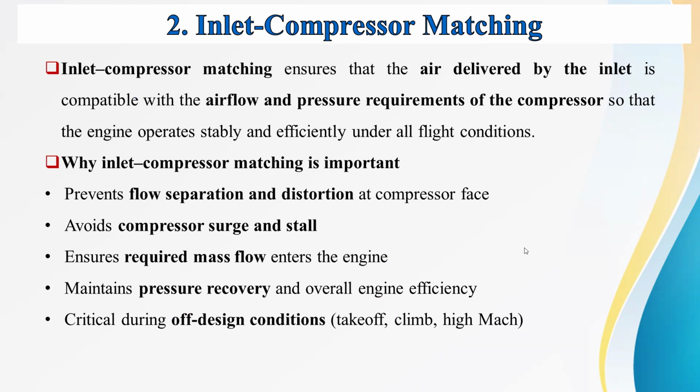Okay, so why is inlet compressor matching important? This is because it prevents flow separation and distortion at the compressor face, and it avoids compressor surge and stall. It ensures the required mass flow enters the engine and maintains pressure recovery and overall engine efficiency.